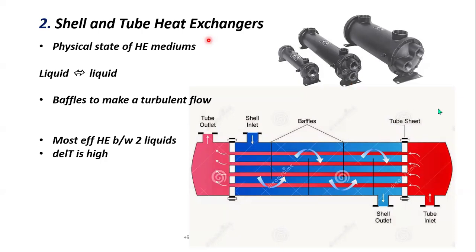Like I told you now, it's not for high heat exchange. We can't say directly it has to be for high heat exchange or low heat exchange. Simply the idea is to initiate a heat exchange between two mediums. That's it. But if you are preferring shell and tubes, the heat exchanging efficiency should be comparatively higher than that of other kinds of heat exchangers. That's the only area. But you know, most of the industries are using shell and tube itself.